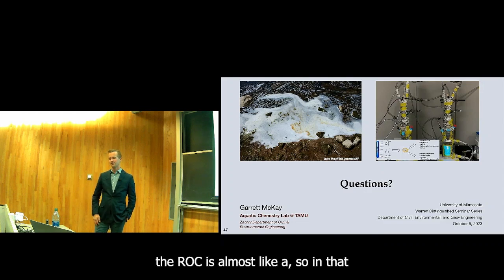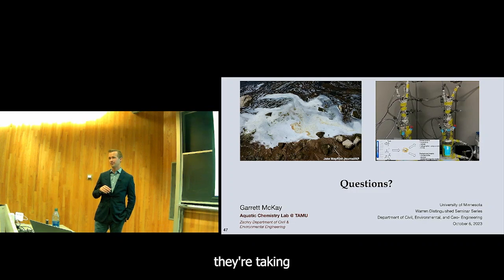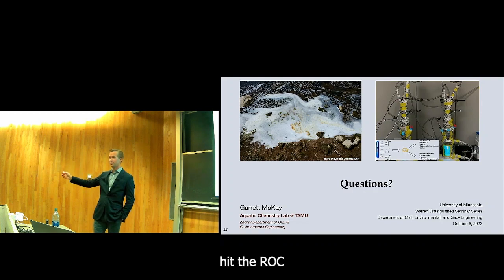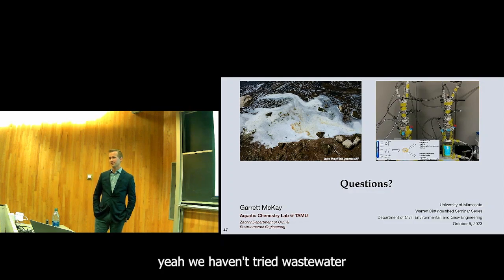In the water reuse facility, they're taking secondary treated wastewater from all over Orange County, and by the time we get it, the water has gone through ultrafiltration and a few filtration steps, it's hit the RO, and we get the reject from that. So we haven't tried wastewater effluent directly.